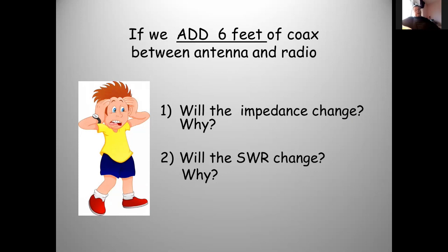The impedance shouldn't change. The SWR might. Can you explain your answers? Because the coax is a 50 ohm feed, and the barrel connector should be 50 ohms, but the electrical length has changed, so the SWR has altered slightly. Do you guys agree with every part that Barry mentioned there? Assume it's a good 50 ohm barrel connector, good 50 ohm coax, yeah.